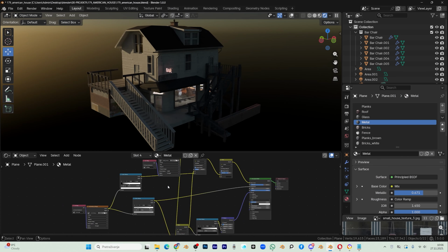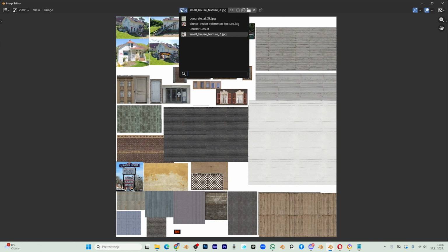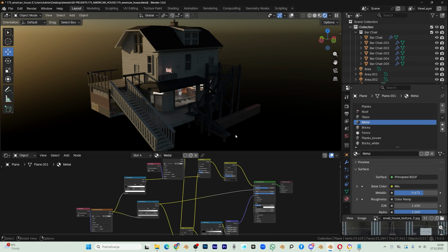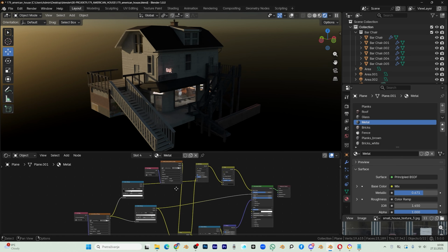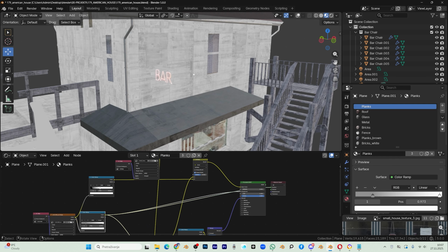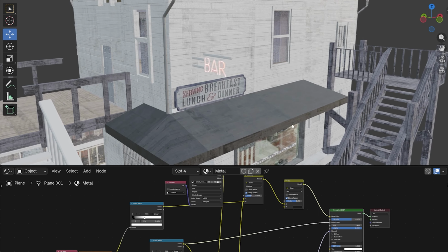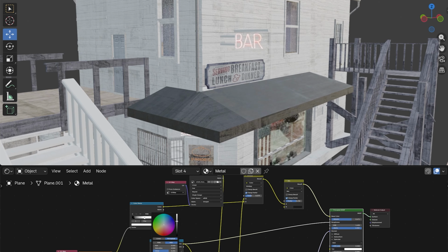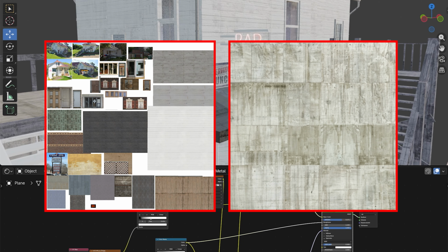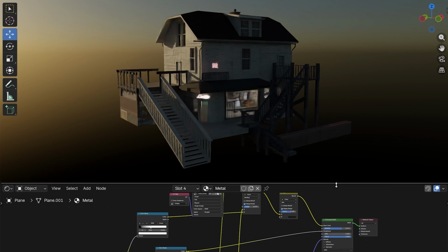And the only thing I use in addition to this texture map is one random concrete texture you can download from the internet, which looks something like this. And with this I just add variation in the color input to add more dirt. I also use this for roughness. I usually use something like a concrete texture for roughness. For example, if I select this material part and increase these dark colors, you can see how this affects the roughness. So the point is that with just two textures, which are maybe 30 megabytes, I built this whole house, and this house still looks good in render preview.